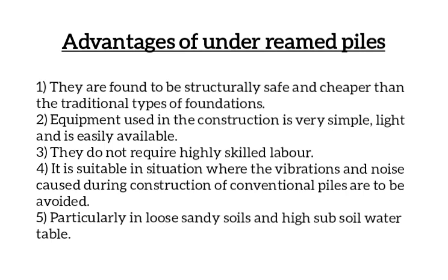The advantages of under-reamed piles are it is structurally safe and cheaper, and the equipment used in the construction is very simple, light and easily available. They do not require highly skilled labor, by which the cost of construction becomes low. It is very suitable for loose sandy soil and where there is high subsoil water table.